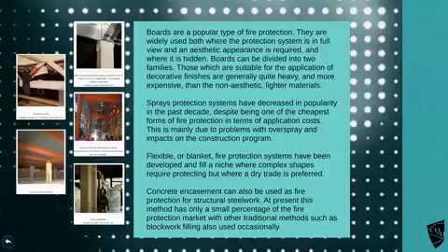Here's a man doing some spraying like there. They're not as popular as they used to be. They're quite messy. You can get it sprayed on the wrong bits and it can float around a little bit. And they are susceptible to impact damage as well. There is this kind here, which is flexible blankets. I wouldn't consider those to be an initial design decision. I think they're more of an afterthought. They're good for really complicated shapes, but they're more of an afterthought for an upgrade, really.